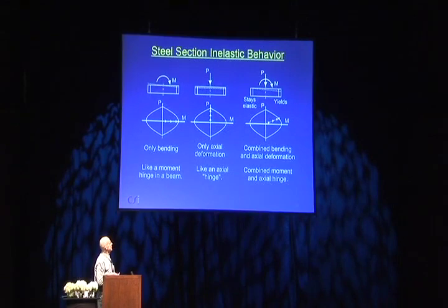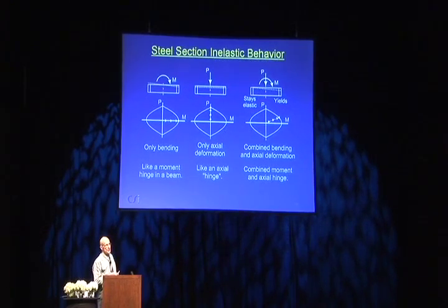A little bit of complication though. Suppose you had just a tiny bit of bending moment to the left, then actually this flange will yield first and this one won't, so actually it'll start to rotate. And if it's a little bit to the right, it'll rotate in the other direction, so it's very sensitive. And you will not get an axial hinge like this because you generally can't accept axial forces of that magnitude in a column. But theoretically it can happen. So it's like an axial hinge.